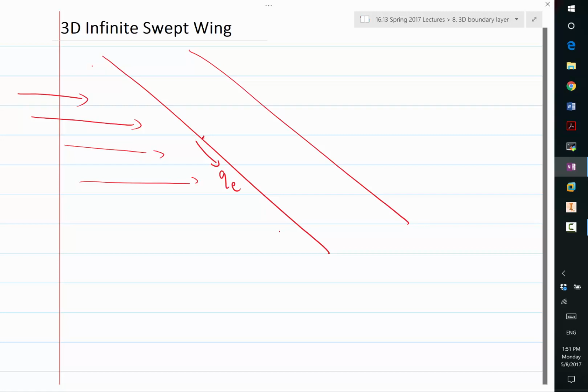Right. Do you expect the boundary layer to be thicker here, exactly at the leading edge, versus here? Just two arbitrary points on the leading edge. So is the boundary layer going to be thicker downstream or thinner downstream? Well, it will be developing as it moves. Right, so it should thicken. So how thick should it go? Should it become infinitely thick downstream?